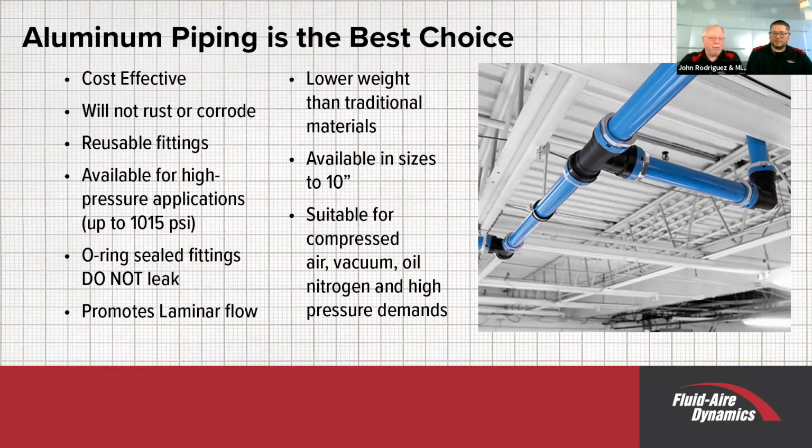We put this pipe up and we're done. We don't have any leaks. We use some of the other with plastic fittings. You put that up, and you still have to go around and make sure that we don't have the leaks that we would have. And we have leaks with plastic fittings, let's put it that way. Again, it's so simple to put up. You put the two pieces together, you hand tighten it, and then you take a quarter turn on the nut, and you're done.